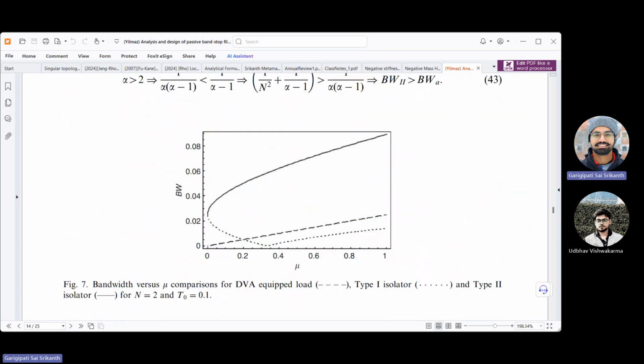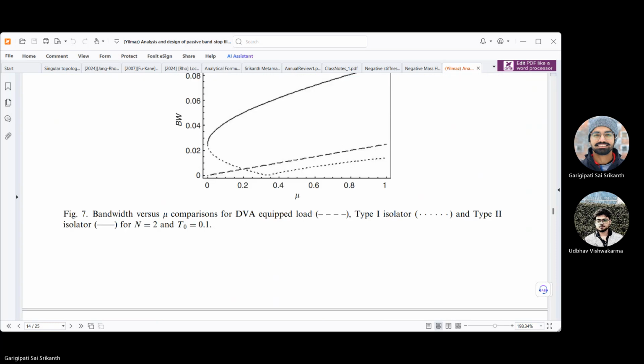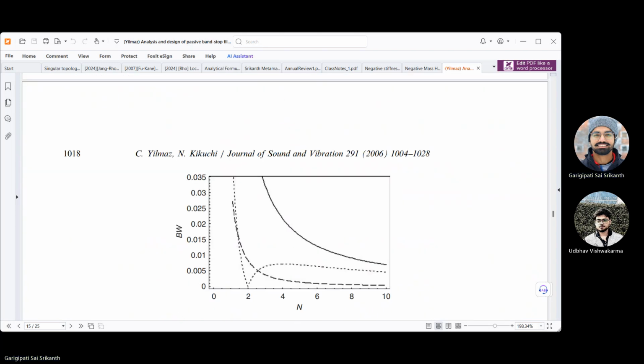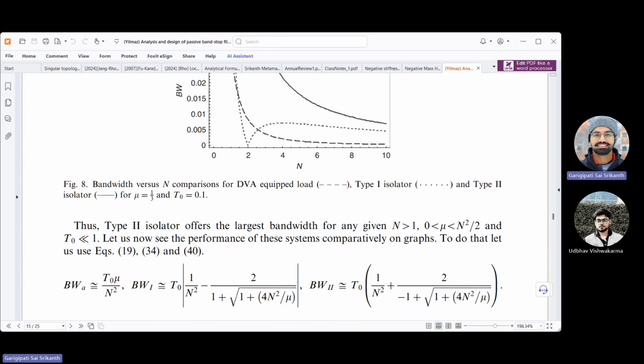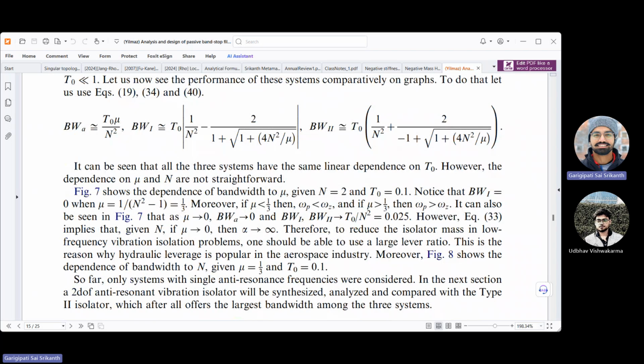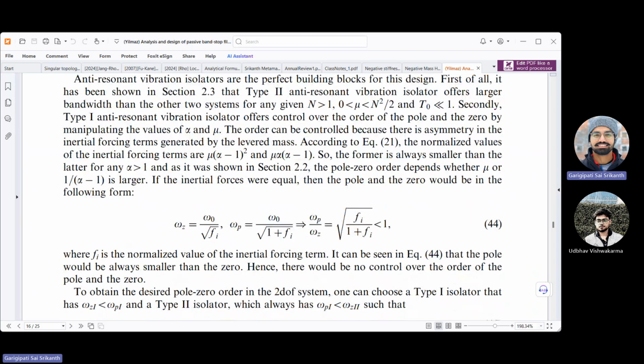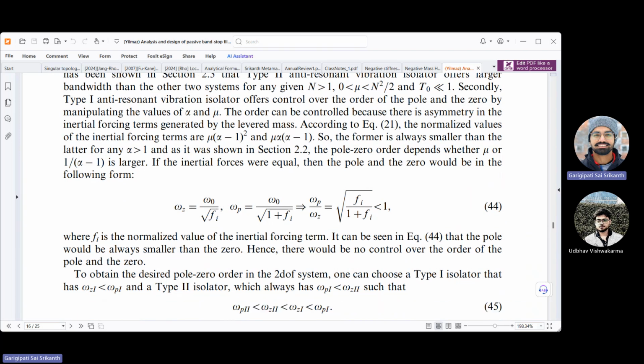Whatever lever arm is best should be selected. But the idea is to use the lever arms to influence the frequencies associated with mode shapes without changing the mode shapes themselves. That is crucial. Do not change the mode shapes.